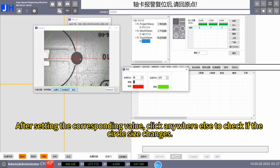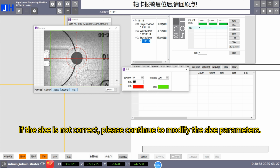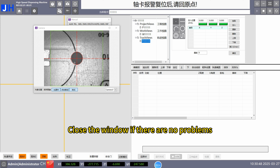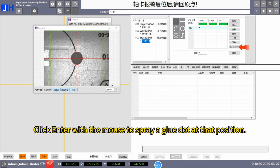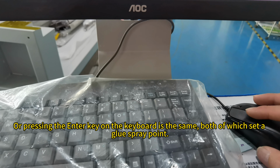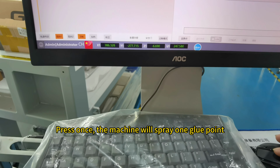After setting the corresponding value, click anywhere else to check if the circle size changes. If the size is not correct, please continue to modify the size parameters. Let's set it to 1.5 to check if it is appropriate. Close the window if there are no problems. Click Enter with the mouse to spray a glue dot at that position. Or pressing the Enter key on the keyboard is the same, both of which set a glue spray point. Press once, and the machine will spray one glue point.